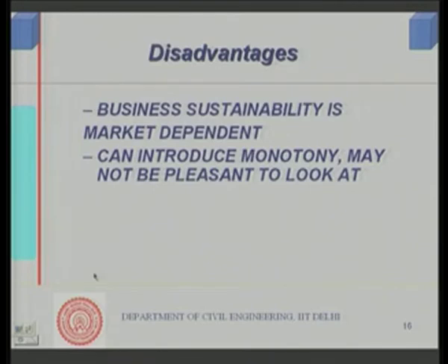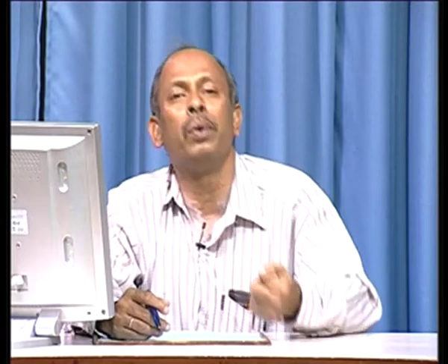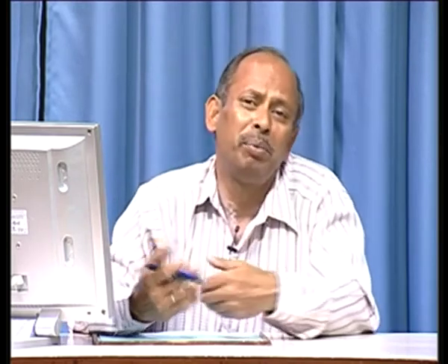Now, let us look at the disadvantages of precast construction. If it is a building, then business sustainability is market dependent. If the market likes your product, fine, but there are examples where precast factories have been closed down because the market did not accept them. They can introduce monotony, because everything is the same, you are producing the same thing several times. So they may not look aesthetically nice, especially in buildings, but architects can take care of this by various means. If properly planned and designed, the monotony one can get rid of.